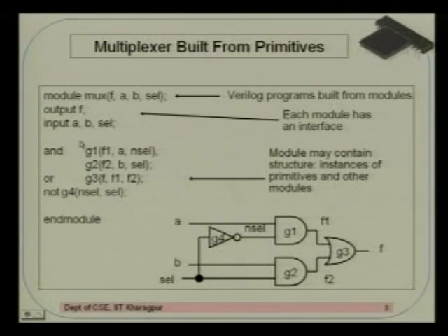In one sense you have a scope of concurrency, but on the other hand you may also have some amount of race conditions involved. So you have to be careful how to implement them, and we will see them as we go ahead. We have different kinds of assignments which we use to tackle these kinds of issues. Right now you can imagine that all of them are concurrent. Let's believe that all of them are being executed simultaneously, that is, in the same timestamp.